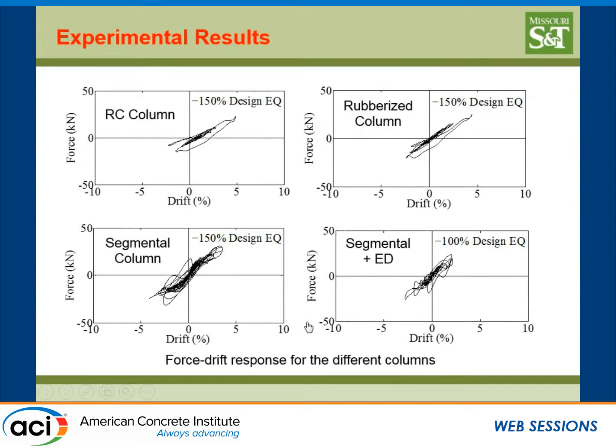Well, here we are looking at the response for different ground motions. So what you have here, you run the shaking table and you just measure how much force. And the way that we measure the force, we have accelerometers at the mass level, and we have a mass times acceleration to give you your force. And this is your lateral force, and you measure the drift at the center of mass as well.